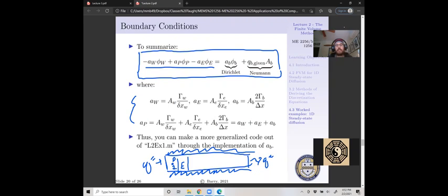So yeah, you can definitely provide decent initialization for the temperatures throughout your domain. And depending upon your initialization, if you are too far out, your system of equations might not converge. It might just diverge into a nonsensical solution.